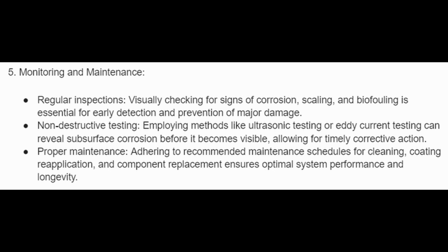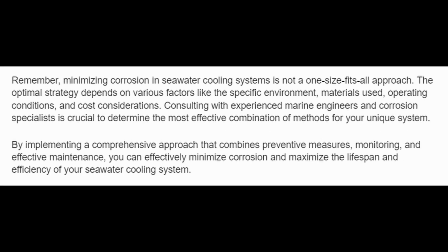Non-destructive testing: employing methods like ultrasonic testing or eddy current testing can reveal subsurface corrosion before it becomes visible, allowing for timely corrective action. Proper maintenance: adhering to recommended maintenance schedules for cleaning, coating reapplication, and component replacement ensures optimal system performance and longevity.